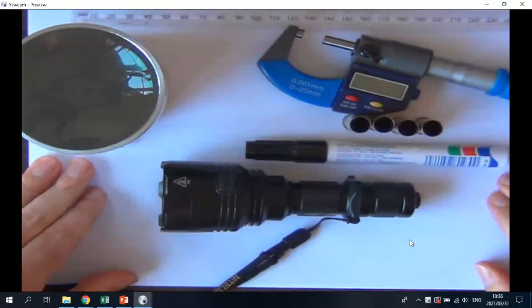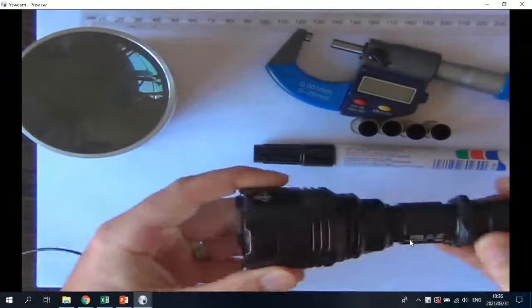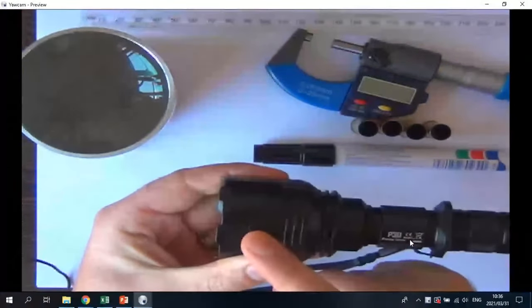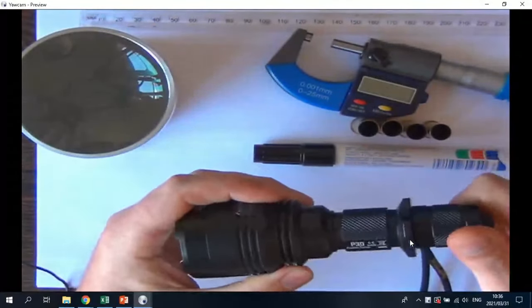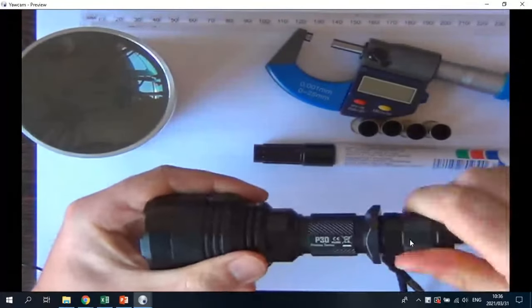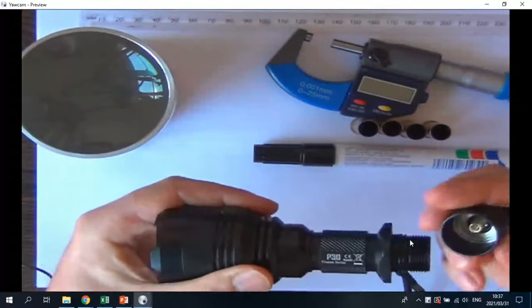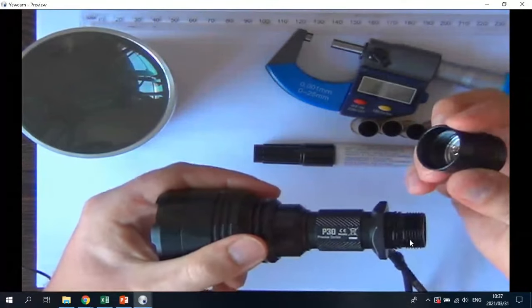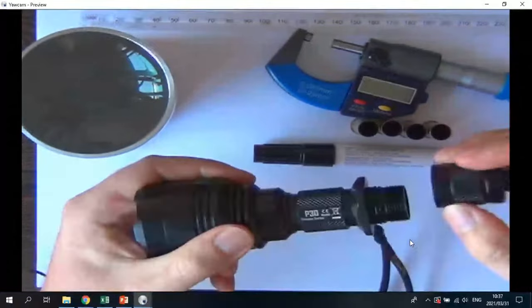So what I have here are a couple of different random objects. This one over here is my little LED torch, and this surface has been altered by means of an electrical process. I won't really call it electroplating, it's an electrical oxidization process called anodizing. So if I just quickly unscrew this tail cap, you'll see on the inside there it is silver. That is the raw aluminium. And then the black on top of that is the electroplating or electrical process to change the surface of the material.